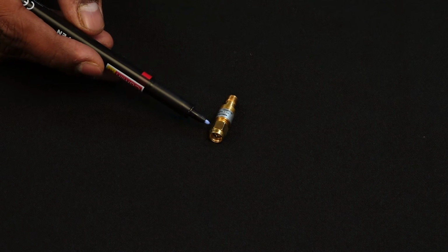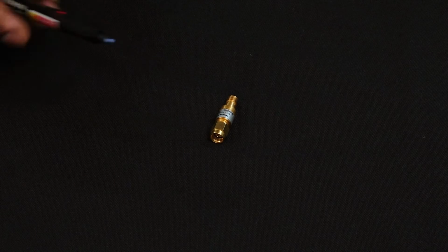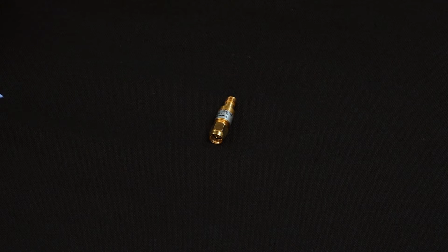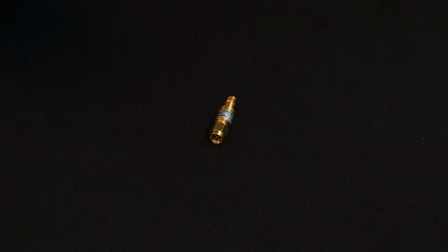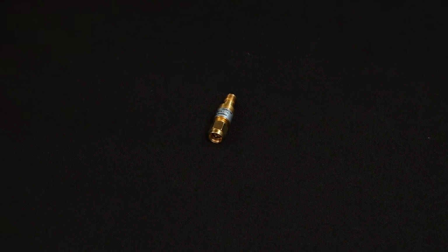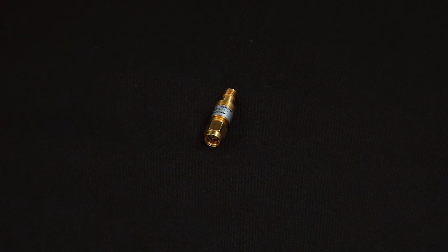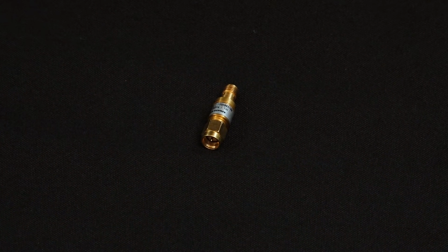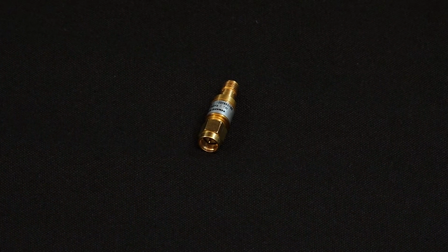So the fifth component that I'm showing you here is called an attenuator. I highlighted the importance of attenuators when I was talking about the TLP setup and showing you the diagram. These attenuators are connected to the input of the oscilloscope because your oscilloscope inputs can only handle a certain voltage range. Say, for example, our oscilloscope can only handle up to 5 volts at its input. When you are applying a signal that is very high in voltage, you need to attenuate the whole signal to under that level.